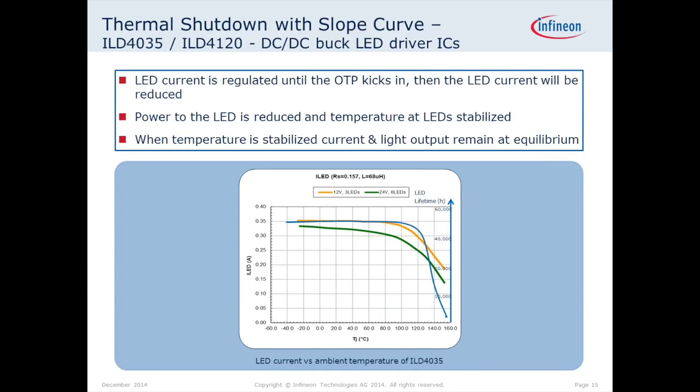And when it's coming to the critical stage for the LED lifetime, the current is basically reduced. And these LED driver ICs are also, as I mentioned before, you don't need to use any external NTC, if you can thermally couple these LED driver ICs with the LEDs, which is usually the case for DC-DC buck LED driver ICs. They're used usually on the light engine where the LEDs are available, then it's a quite good solution. Let's still discuss the advantages and disadvantages.